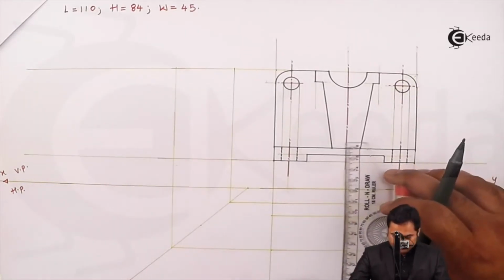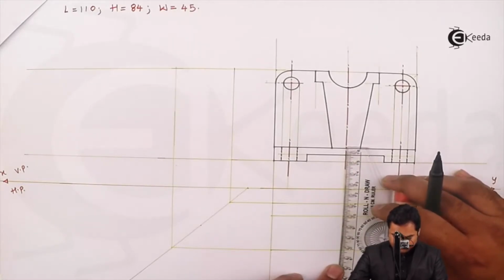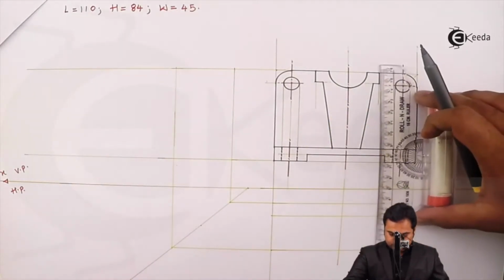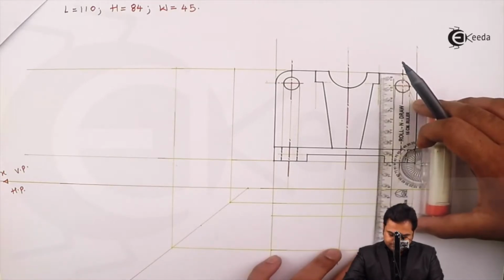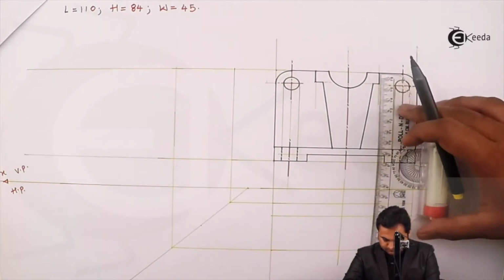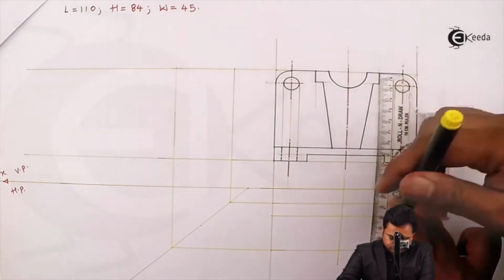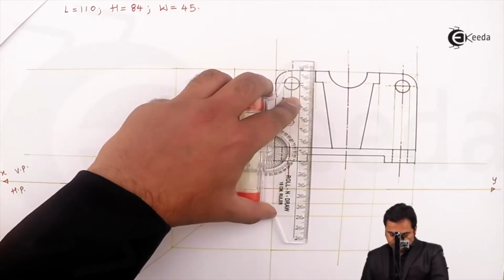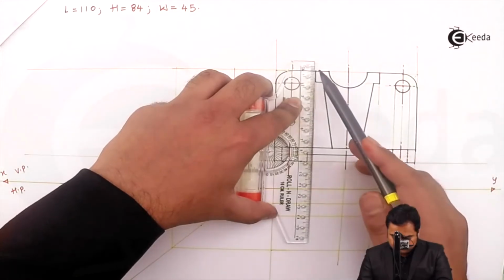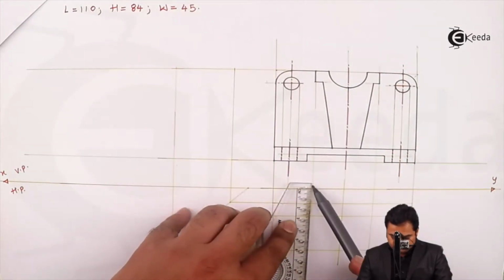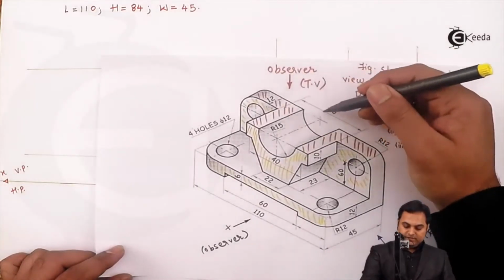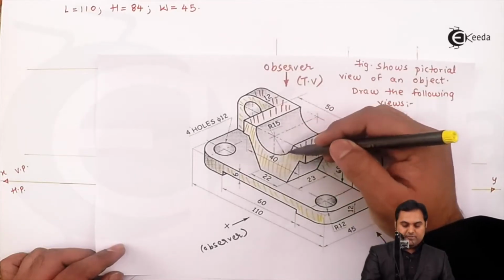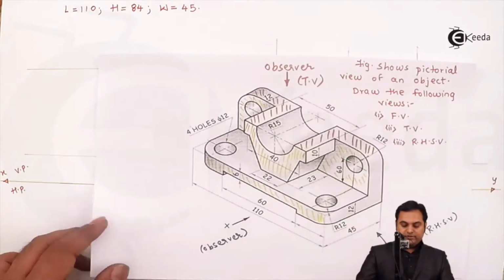And just before that, I'll also take this center line, which acts as a reference for us. Projecting it light. After that, taking length equal to 50. Here, this semicircular portion is there, which is having 30 mm length. I'll project that portion to get these two rectangular surfaces.